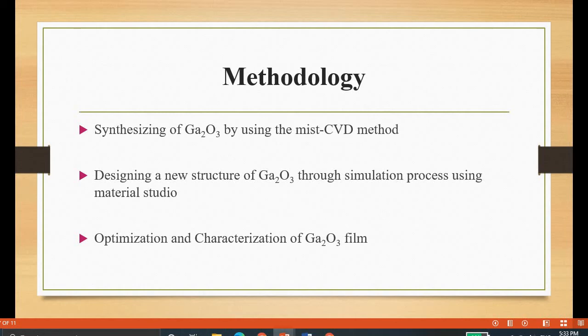This is to observe the gallium oxide thin film structure without any significant lattice mismatch between the gallium oxide and sapphire substrates. All the structural analysis will vary with the different parameters I mentioned previously, which are the temperature of the heating furnace and also the flow rate of the gas.